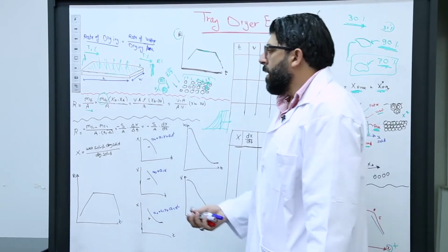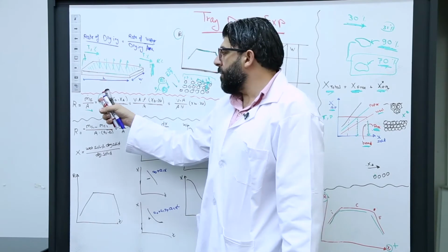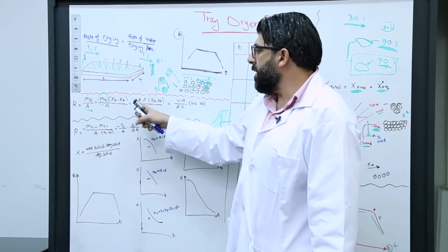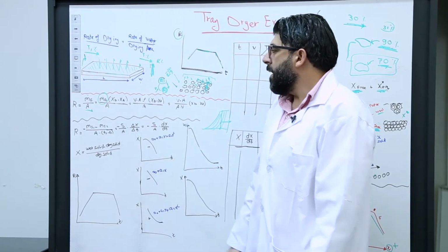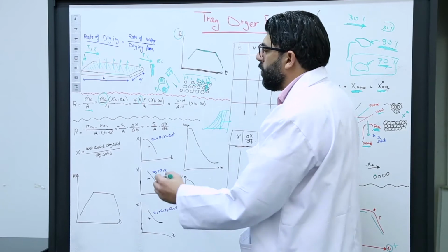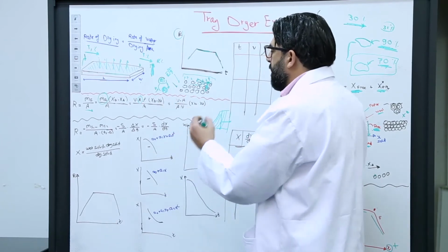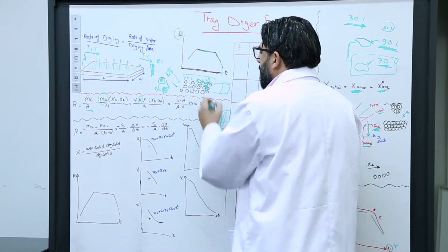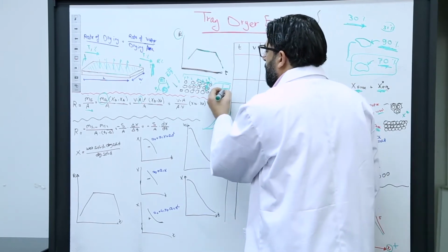Now, mass flow rate, as you know from fluid mechanics, equals velocity times area times density. And the area here is the cross-sectional area, so it should be the area the air passes through in the duct or tunnel of the dryer. So we have our tray inside.